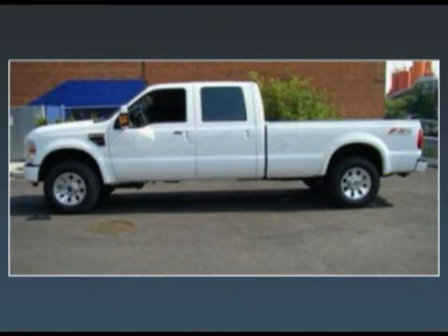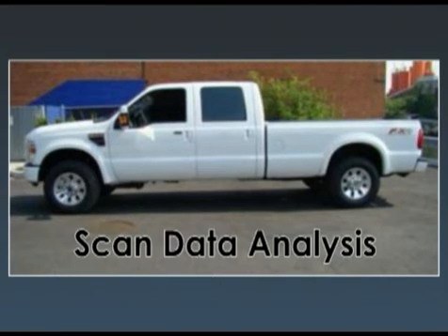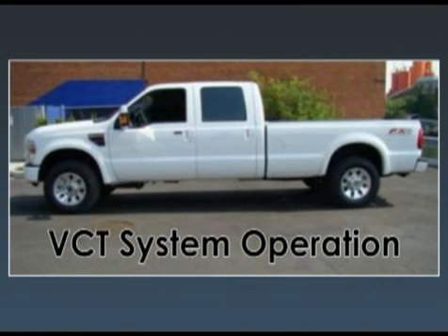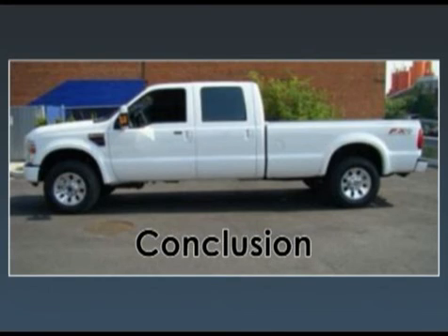Okay, we still have this truck in here. It's got trouble codes and we need to fix it. Jeff gave us an analysis of the scan data. Have you been able to draw any conclusions yet? We also learned how the VCT system advances and retards the camshaft. So as a summary, oil pressure is needed to advance and retard the cams. We agree upon that. Cams on this vehicle retard when the engine RPM increases but do not return to normal position at idle. Have you come up with a conclusion yet?